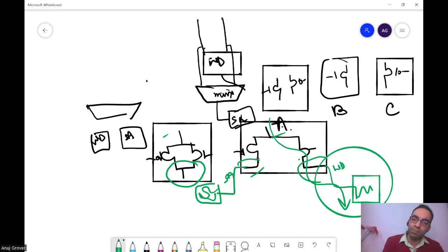What I am saying is there is a bigger thing, not just this one transistor's junction capacitance getting added. There's a lot more coming into the picture. Sir, I think Raghav meant if we use shared diffusion, then the capacitance reduces at that node, if I'm not wrong. Can you use a shared diffusion between an NMOS and PMOS? No, sir. Okay.